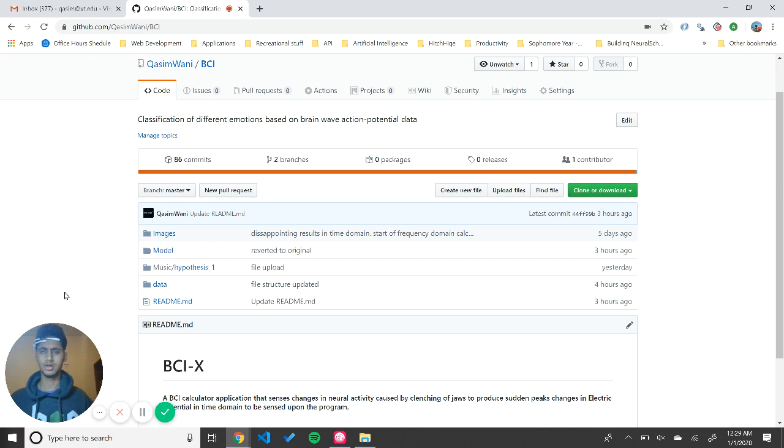Well, it really depends on the type of BCI that you have, but the one that I have sends electrical impulses, or the change in electric potential at the scalp or the surface of your brain. You can't really see, but I have five electrodes, a five channel sensor, and they're located in three different regions of the brain. Two of them are in my temporal region, one is in my parietal, and two others are in my frontal regions. The purpose is to measure the changes in the electric potential as a function of time.